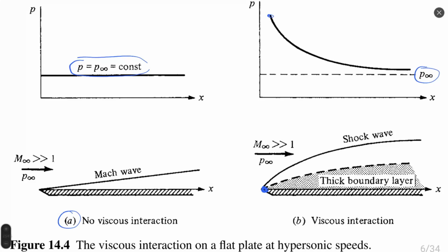In case of absence of the boundary layer, we will not see this initial elevation of pressure, but the calculation would be significantly simpler. In case we need to see this initial behavior of pressure on the body, we will need to calculate, and let's say better numerically simulate, the flow with a viscous model.